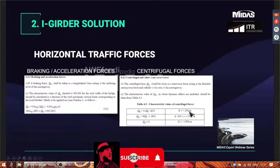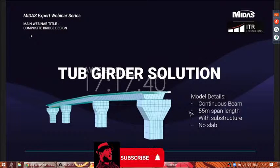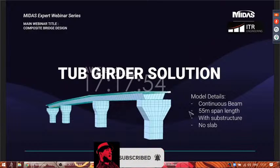With the first model, considering the wall deck package, we reach a section of about 1.6 meters. Due to the presence of an underpassing intersection, we had limited space. In addition, the ramp needed to be shortened since in the first version of the project, it got too close to some buildings near the road. This further reduced the available clearance, making the first section no more suitable.